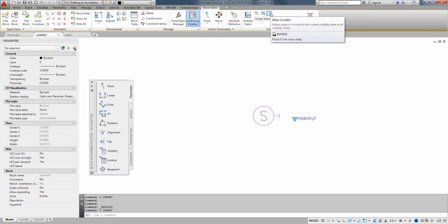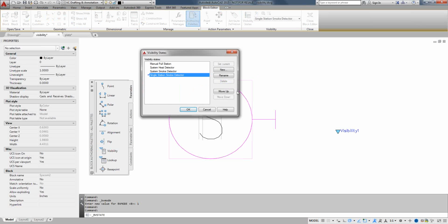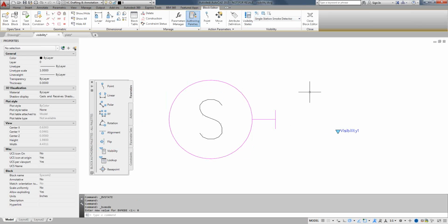All right, so a couple things here. I could now make this invisible. I don't want that. I did that all in that dialog where it said, hey, do you want to keep them showing or not? But what I can do, if I want to just kind of see how things overlay, I can use this visibility mode. And it shows me the highlighted one, the very dark one, is the top symbol, and then it shows me how the rest are layered underneath. So it does allow me to see, is everything in the right area to have a common base point. So a good way to check all of your visibility or location for the objects.